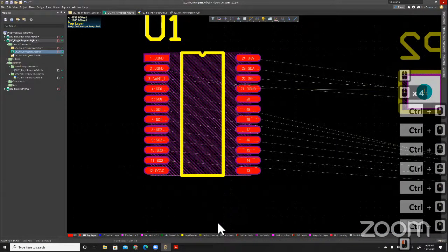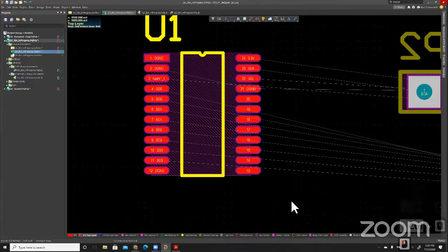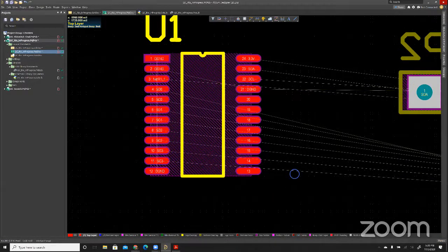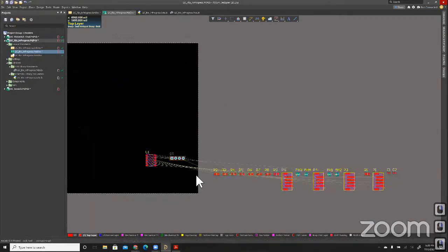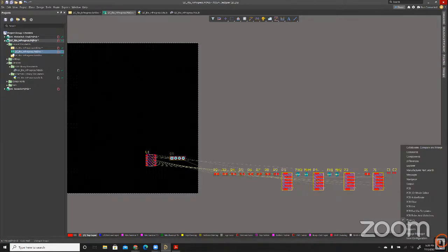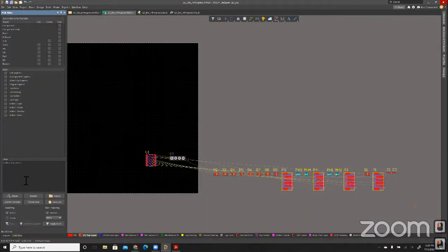Let's see, was there another thing to explain with the layer stuff or the PCB? Yeah. So you'll also notice this is kind of just an introduction of some of the things that you can do in a PCB doc. Remembering that I said that those PCB panels down here can be important. If you go and do PCB Filter and add that in here, you can add in a filter and then decide what it is that you want to do with it.